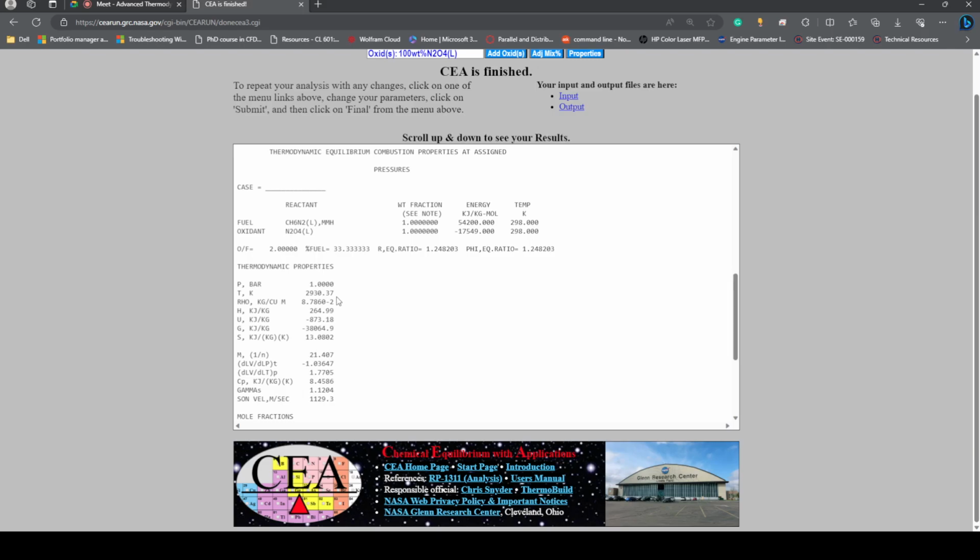The blades will be able to take only a certain amount of thermal load. They will be fine only at a maximum temperature of 1600 Kelvin. So if you send a gas of 2900 Kelvin, it starts melting. That should be avoided. So for all these engineering analyses, we require the adiabatic flame temperature analysis. That's why people do this CEA analysis at first.